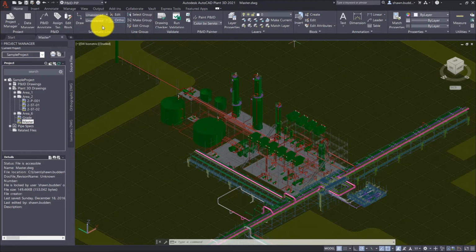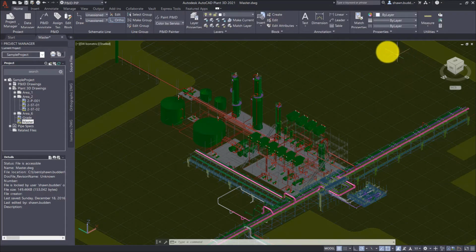Now, maybe you want to have a specific setting. So let's talk about how you can change it so that you can have more convenience in your working. Let's go ahead and move a couple of things around. Let's say we're going to build something off of the P&ID PIP environment. And let's say that you really don't need this annotation tab for some reason. Just right click on your ribbon right there, and then you can take off or show anything that you want in the ribbon. You can also control what you want in the tabs. Go ahead, switch those up any way that you like. Uncheck, add to it. You could even undock the ribbon and put it somewhere else. In other words, make any changes that you want.